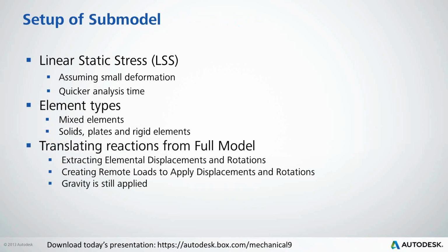The submodel, again, we're going to use linear static stress analysis, assuming small deformation, and again, the benefit is much quicker analysis time. But with this one, we're going to have mixed elements. We're going to be using solids for the base plate and the foundation. We're going to have plate elements to represent the beams, and we're going to be using rigid elements to help translate the point loads that we'll be getting in the full model to a more three-dimensional object.